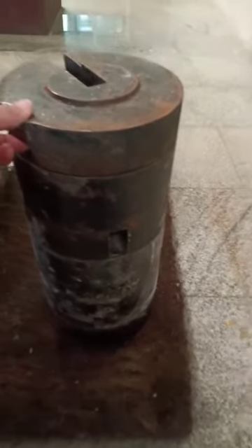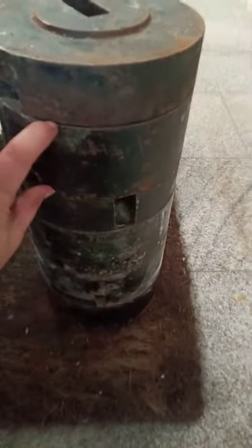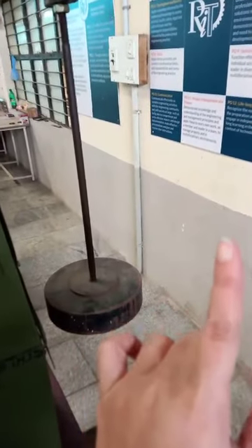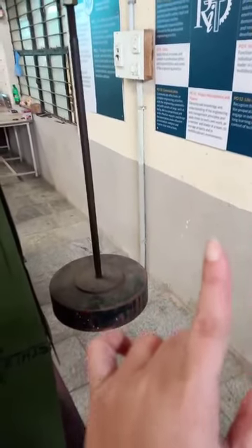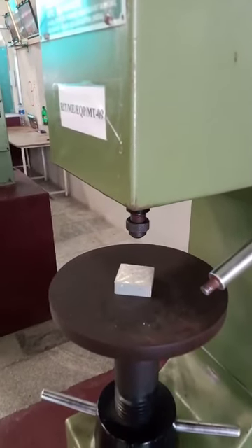Here this one is 250 kg of force. Whatever the thickness, as compared to this one it is large. Then this is 500 kg of force. The total amount including this 500 kg of force is 3000 kg of force. That we have to use for ferrous material, that is mild steel. Here 500 kg of force we have to use for the non-ferrous material, that is aluminium.